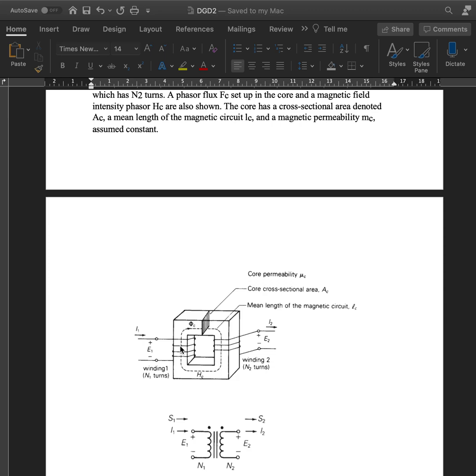a distribution area where they would step down the voltage, increasing the current, and then they will transmit it to the residential areas. And even some residential areas might have a smaller substation where it will be stepped down further to become usable for a house. Sometimes if you see a pole, especially a wooden pole with a box on it, that's a transformer right there. So it's converting the voltage coming in from high voltage to a low voltage that will come to your house, and the large current that is generally used by your devices.